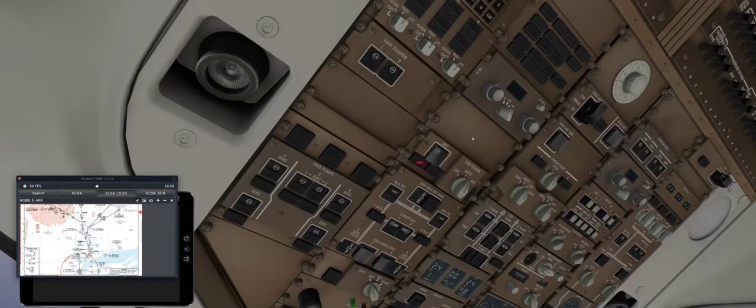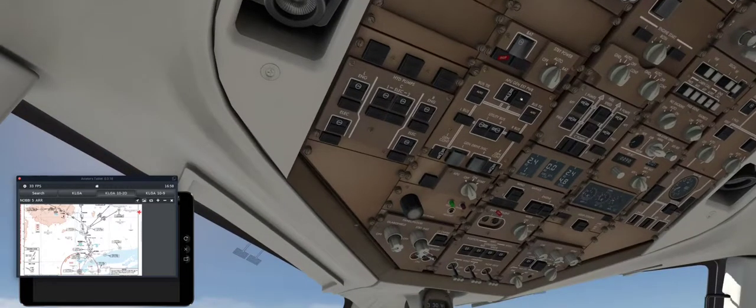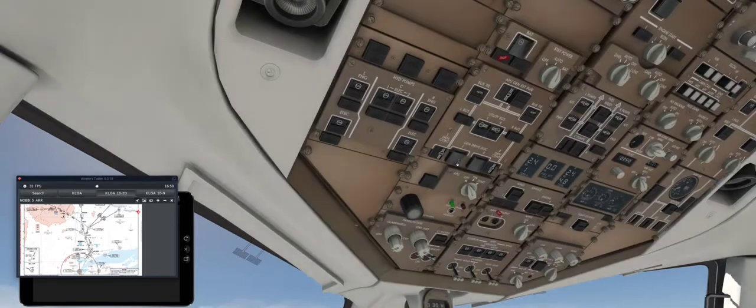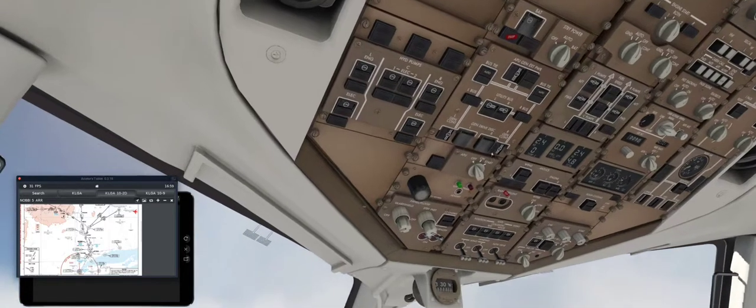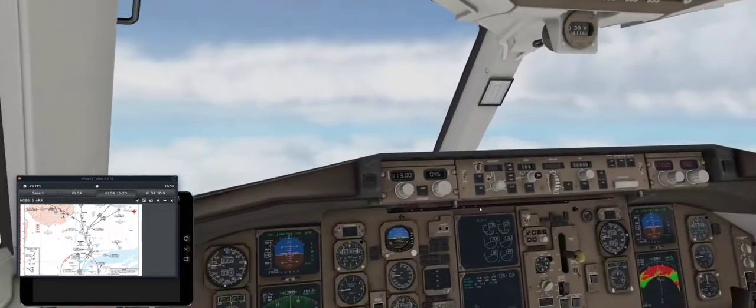Yaw damper is just part of the system that keeps the aircraft flying straight. You don't really have to do much with it. Our power panel, which we used to transition from ground power to APU power, and then finally we're now on generator power. Don't open these. They're covered with glass for a reason, so that you can't just bump them and press them. You don't press these, except the only time you do is if you ever need to physically sever the generators from the engines. Why would you do that? If there's a severe engine problem or severe generator problem, you might want to do that. But guess what? Once you push that button, yeah, it's a ruined engine and/or generator. And so don't push those. Don't fly with your APU on. You'll burn extra fuel. That's not good.